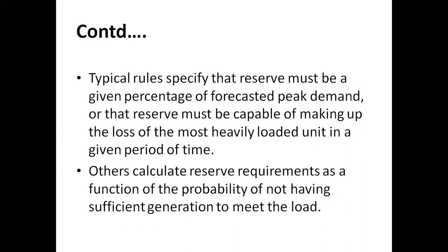For those load characteristics, we must concentrate on the peak demand of that particular system. Depending upon the forecasted peak demand, if I make the reserve accordingly, we can counter that particular peak demand.